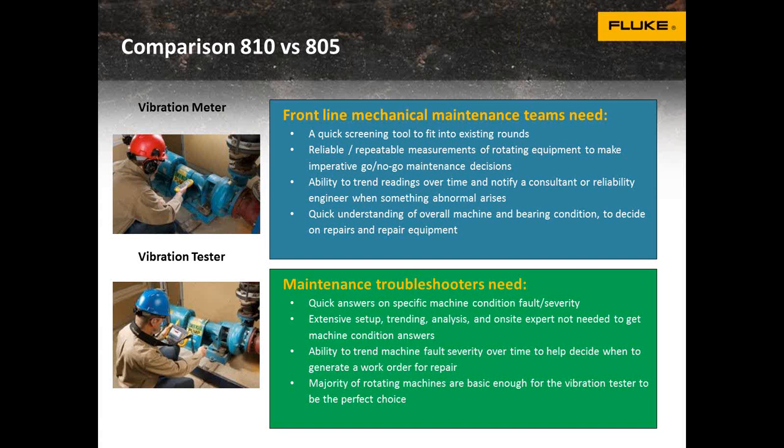That's right. This device is set up so that it collects the raw time waveform, and then it converts it to the frequency, and all of the rules are written in frequency spectrum analysis. So this is not a real-time analyzer or even a vibration analyzer. It's not a tool for a vibration expert to be able to trend and do any analysis.